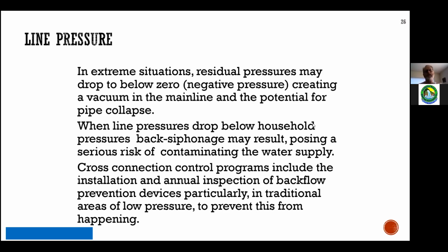So later on in the program, we'll talk about valves and their selection and usage and sizing. And air valves are critical, because when there's a water main break or high demand, if the grade line drops, to prevent a vacuum, air needs to be brought into the pipe. But negative pressure means that the energy, that column of water, 30 meters, 40 meters, 90 meters high, is now below the actual service connections to our residents.